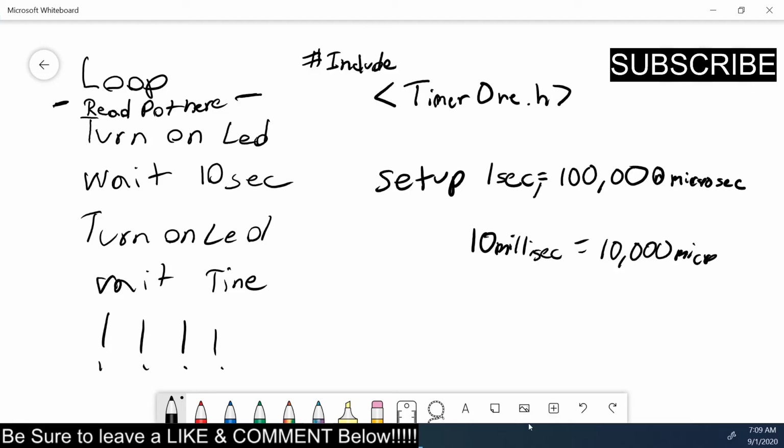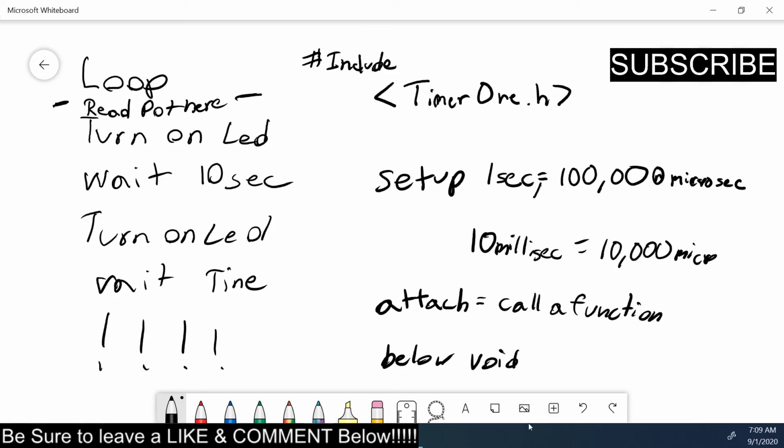So you're going to do that in the setup, and I'm going to walk you all through that. And then you need to attach the interrupt. So you need to attach it, and then what you attach it to, it's going to call a function. And that function it calls is going to be below the void loop. Below void loop. So after that last curly bracket.